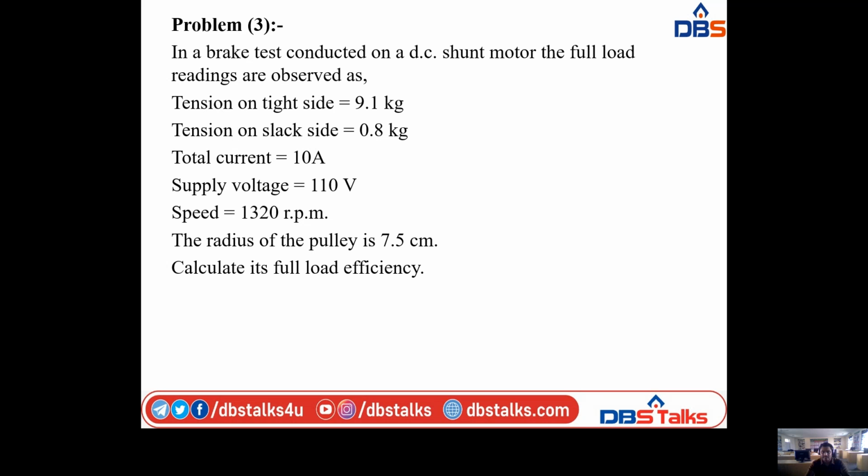Okay, and next they given the times: t1 is equal to 25 seconds and the next one is 6 seconds. And W, you know the formula, W is equal to W dash into t2 by t1 minus t2. I already explained this formula in the retardation test explanation. So from that I am writing W is equal to W dash into t2 by t1 minus t2. W dash we just calculated is 2300, into t2 value 6, by t1 minus t2, that is 25 minus 6, and finally we have the power, that is 726.31 watts, and they given the stray losses, that is 726.31 watts.